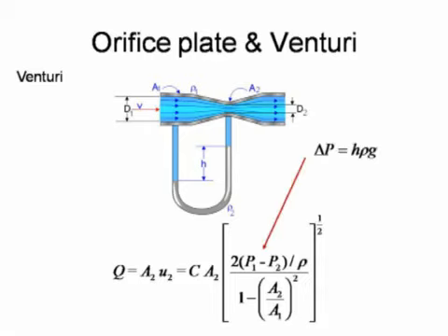Of course we can now substitute in for P1 minus P2, the pressure difference, and we can substitute in the equation depth times density, the static head equation. If we do that, we can then cancel the density terms out, but that sort of hides a secret, because bearing in mind the density in the square brackets has come from Bernoulli's equation, that's the density of the process fluid, the fluid flowing through the venturi or the orifice plate. So really that gives us the pressure measured as a height of process fluid, normally liquid,